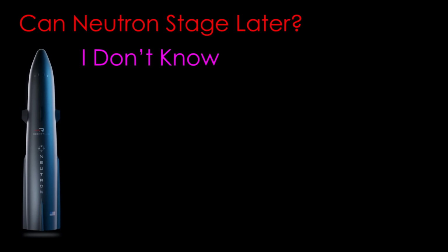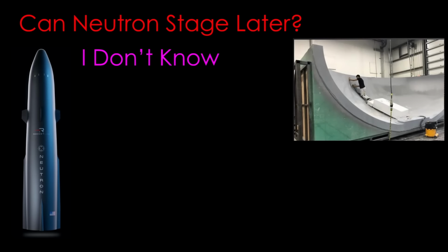Rocket Lab needs to be flying payloads on Neutron quickly, the same position that SpaceX was in when they built Falcon 9, and therefore they will likely be conservative in choosing a staging point. They have the added issue that carbon fiber rockets require carbon fiber molds, and that makes it slow to do experimentation. They just can't add rings like SpaceX can add to Starship. This is especially true with the complex shape of the Neutron booster.